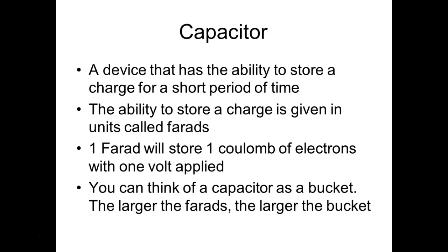This is a device that has the ability to store a charge for a short amount of time. In fact, you can charge the capacitor up and lay it there, and it'll discharge through itself, because that's just what they are. It's almost impossible not to have a current path through a capacitor, right? You understand that? If I've got two electrodes and I've got something in between them, then I've got a current path. There's no such thing as infinite resistance, right? You understand that, first of all.